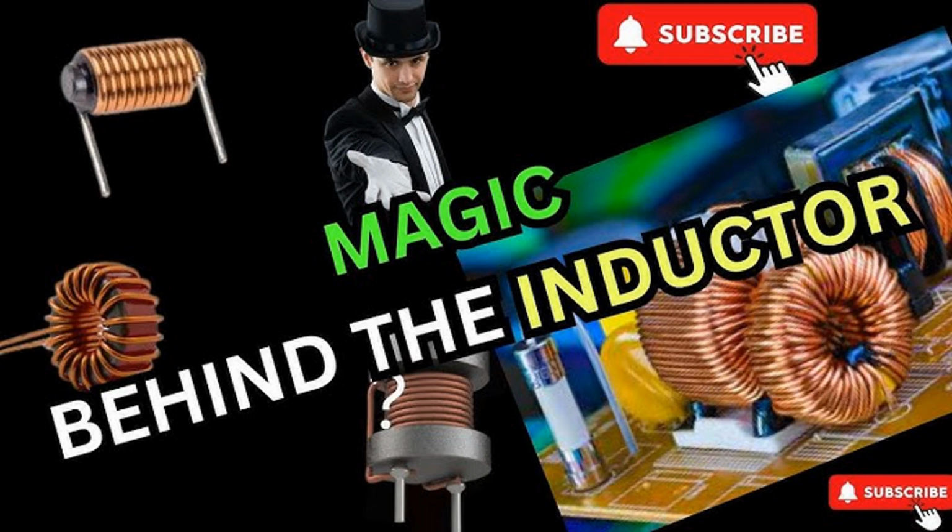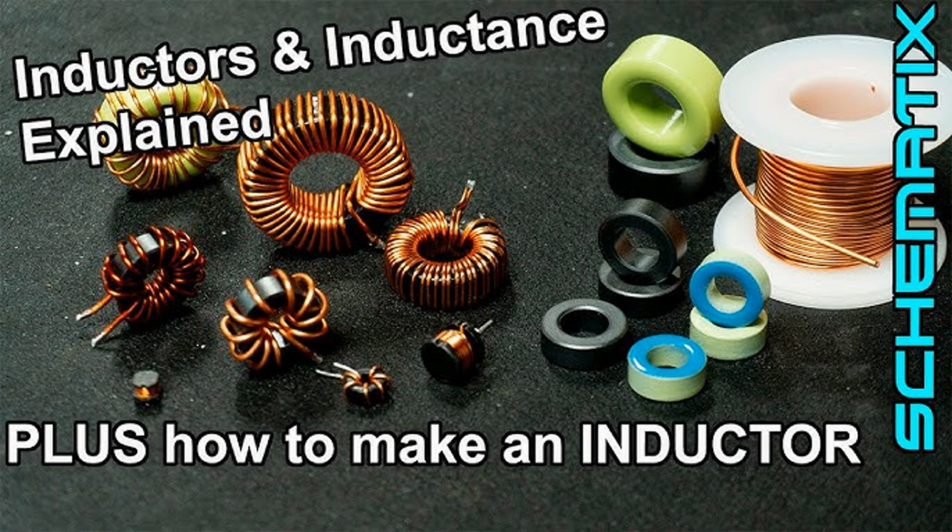Current limiting with inductors. Function: inductors are used to limit the amount of current flowing through a circuit by opposing sudden changes in current. This is due to an inductor's ability to generate a back electromotive force (EMF) in response to changes in current. When a current through an inductor increases or decreases rapidly, the inductor opposes this change by inducing a voltage in the opposite direction, thereby limiting the rate of current change and preventing current spikes.